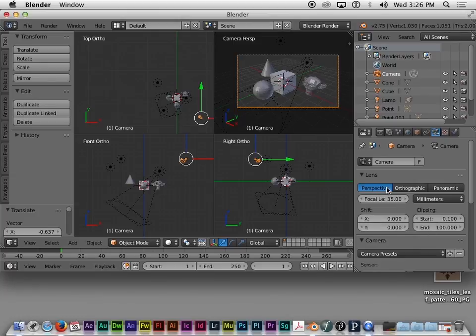Number one, you can change the effect of the lens on the scene. It gives you the option to switch between what's called perspective view or orthographic. Perspective gives you image distortion or natural distortion like a lens would. So there's a vanishing point system, which is controlled by a slider or a value down below by the focal length of the lens. The smaller the focal length, the wider the scene is. The larger it is, the more telephoto or squished the scene will appear.